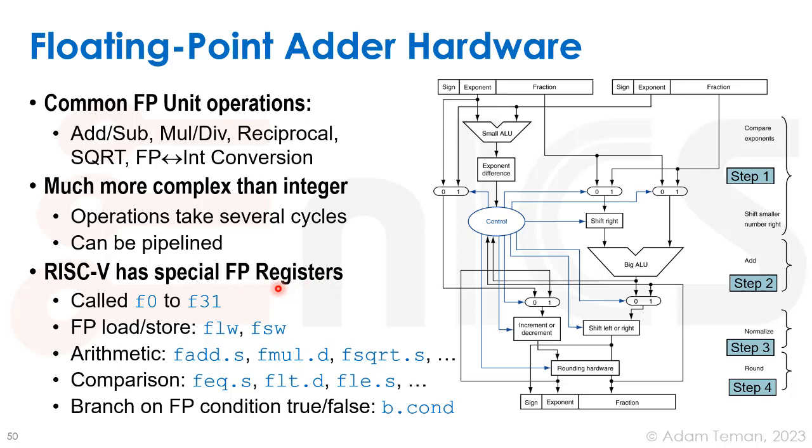What they decided to do is, if you want to have a floating point unit, you'll have another 32 registers called F0 to F31 that will be only used for floating point operations. So you will not mix floating point with general purpose registers, and that's based on the fact that floating point is not used for any type of control or addressing at all. So we'll give it its own registers, they will be separate, and we won't have to mix it in with the real complexities that we might need to use with our general purpose registers.